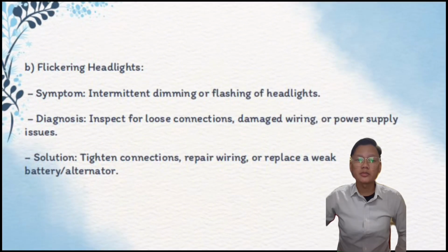Flickering headlights. Symptom: intermittent dimming or flashing of headlights. Diagnosis: inspect for loose connections, damaged wiring or power supply issues. For the solution, tighten connections, repair wiring or replace a weak battery or alternator.